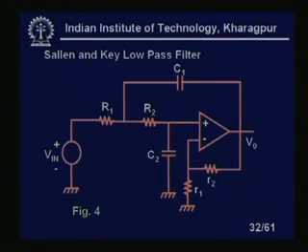So, this is the famous Sallen-Key low pass filter, using a single amplifier structure where we need 4 resistors. These 2 resistors, small R1 and R2, have different values and will determine the negative feedback which you are giving in a positive feedback circuit. This is your RC network, so it is a positive feedback topology because the RC network is in the positive feedback path.